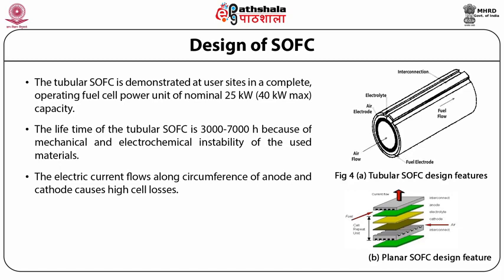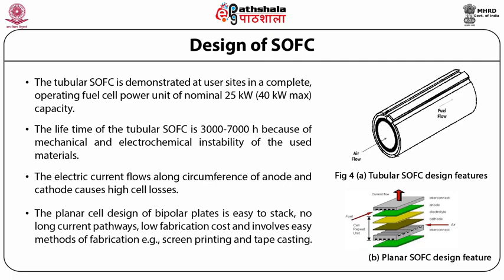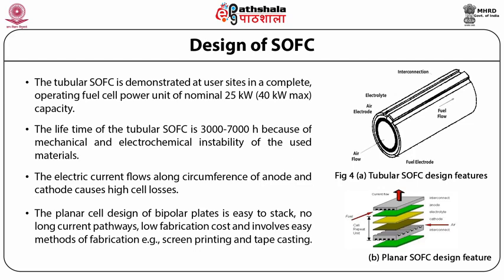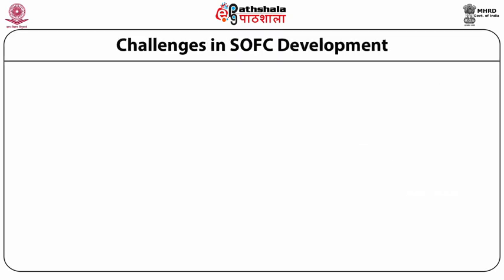Another type of SOFC design is the planar SOFC design. The planar cell design of bipolar plates is easy to stack, has no long current pathways, low fabrication cost, and involves easy methods of fabrication, for example screen printing and tape casting. The drawback in the planar design is thermal expansion mismatch between ceramic and support structure, leading to problems with gas sealing. Challenges in SOFC development.